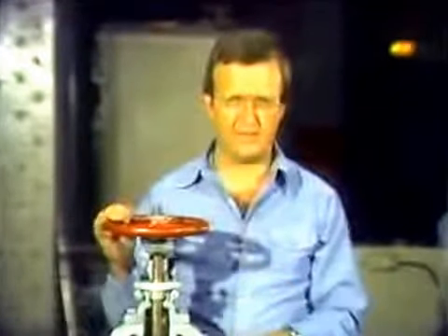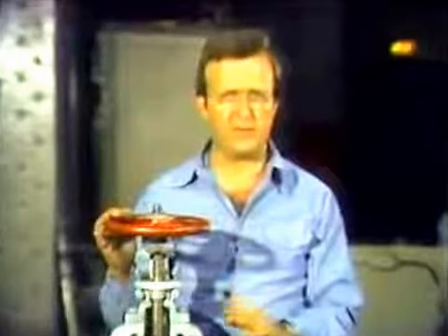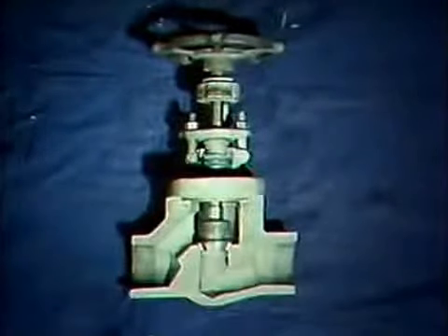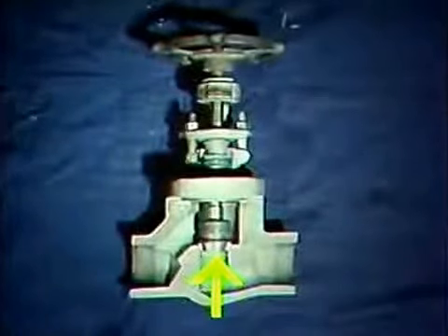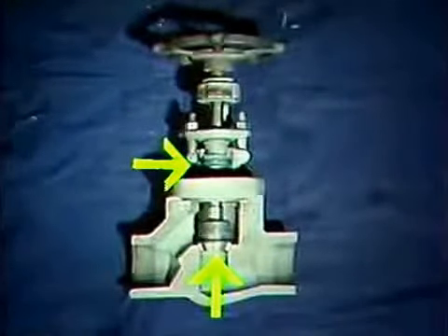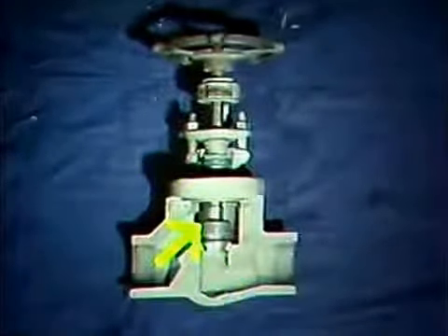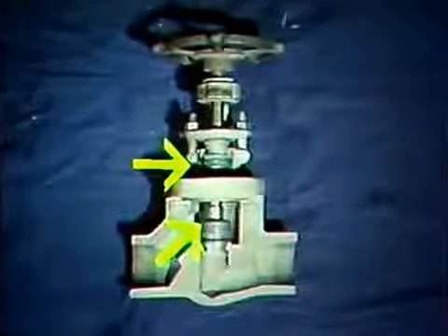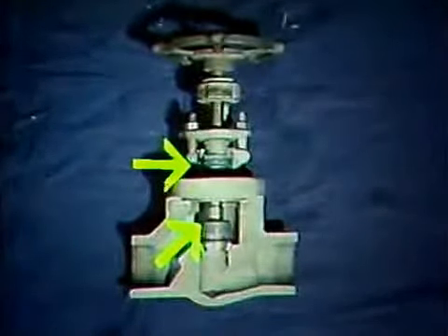Anytime you replace a valve in a system, you must be sure that the replacement valve meets the same specifications as the original valve. It must be installed to allow proper flow from the system through the valve and out again. Normally, a valve is installed so that the high pressure from the fluid or gas is under the disc when the valve is closed. In that way, there will be no pressure on the valve packing, and this reduces the danger of leakage at the place where the stem goes through the bonnet. If the valve were installed incorrectly, the other way around, there would be pressure on the packing when the valve is closed. In this case, there could be leakage that would require more maintenance.